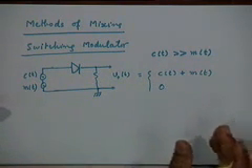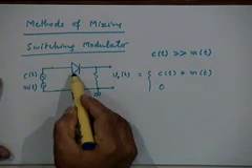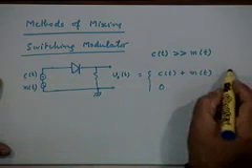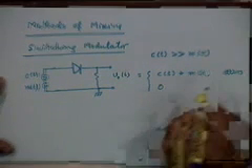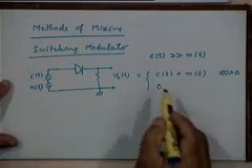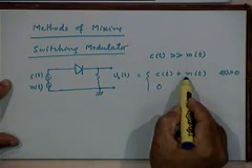If that assumption is true, then it is clear that whether the diode is forward biased or reverse biased will be essentially dependent on the carrier voltage, right. So whenever the carrier is going through a positive half cycle, the diode will be forward biased, and the output voltage will be nothing but equal to the input voltage.